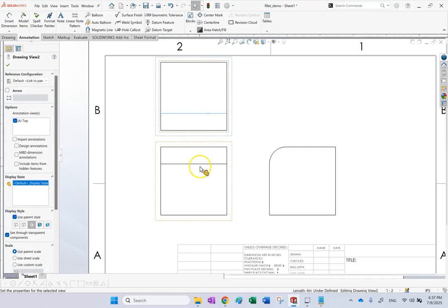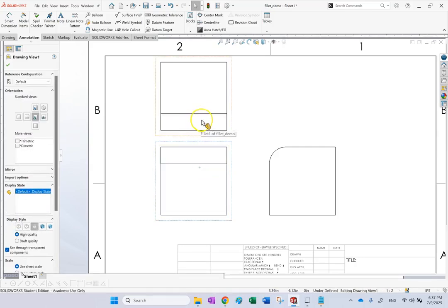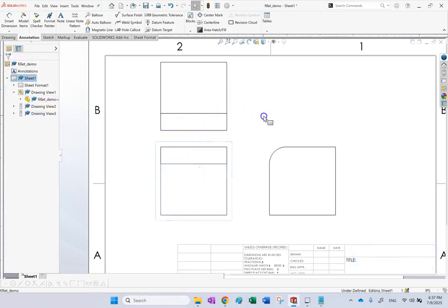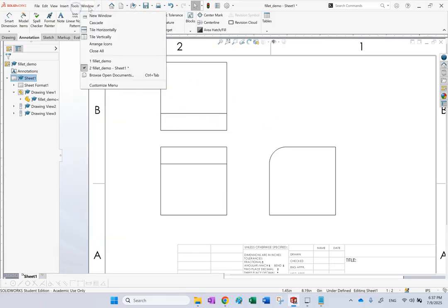And if I just use one view in this case, which of course is not enough, you might say, okay, is this, for instance, a fillet or what? Because if it's just these two, you can easily say it could also be a fillet. So you need this extra view to see that it's a chamfer. It could also be a fillet or anything else. So these lines could be a little bit misleading. So can I get rid of them?